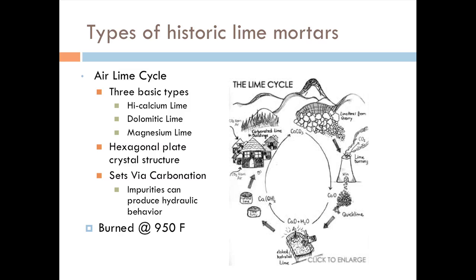So when you have this calcium hydroxide, you add sand to it, and you mix it, and you lay a brick with it, you lay a stone. That is mortar. That's the essential basics. And you could even use that to put it on the side of a house, or what many people might see in this region as an old stone farmhouse.